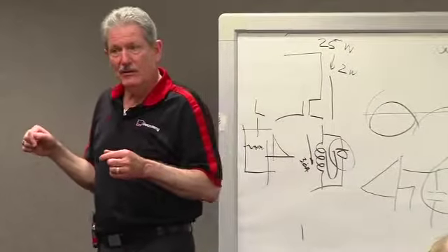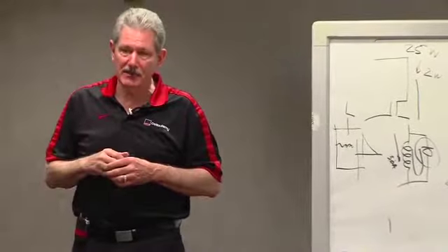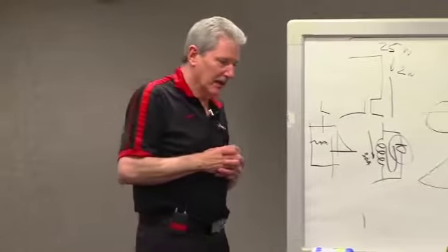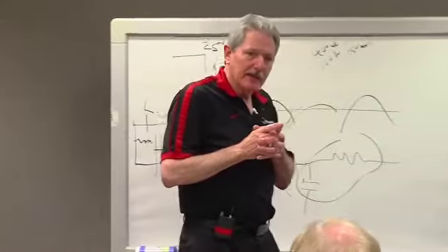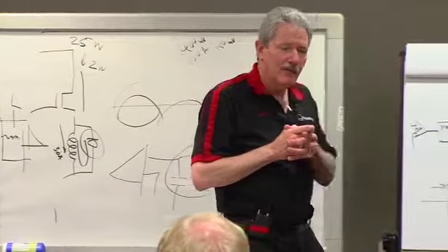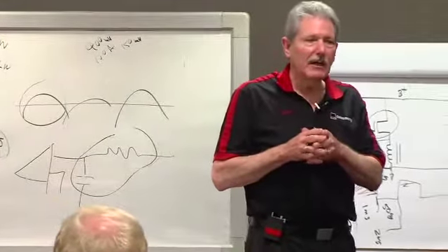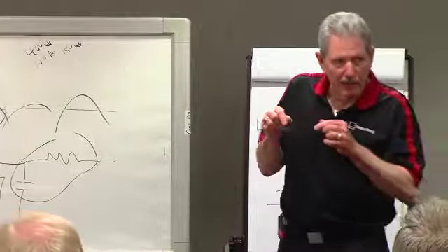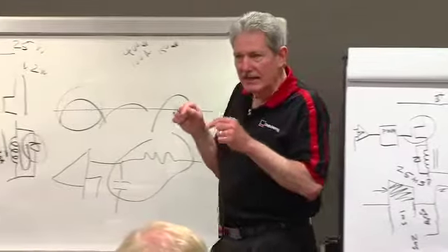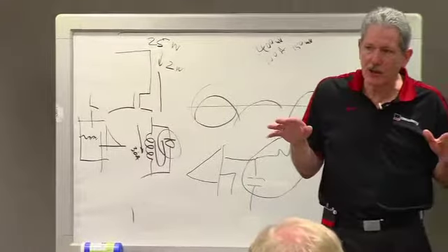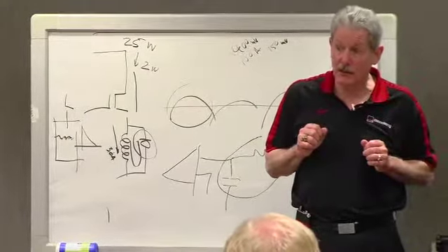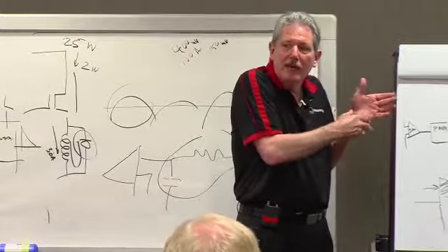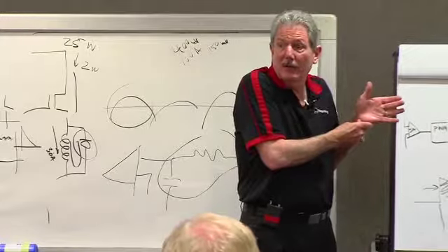So then Remy said, let's get rid of our NTFs. Because back then, 90% of the failures were trouble not found. In order to do that, you have to have a more comprehensive fault diagnostic. With the 9SI, Remy went out to the field and said, if the light doesn't come on, don't take the alternator off. But in order to do that, you've got to flesh out your fault better.